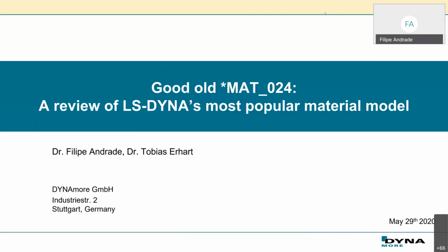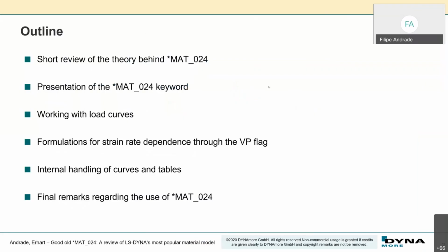So I'd like to start by giving you my outline. I will start with a very short review of the theory behind Mat24. It's just one slide, not much more than that. And then I will show you the keyword of Mat24. We'll talk a little bit about how to work with the load curves for this material model. And then we have a certain discussion about how to formulate strain rate dependence through the VP flag that you have in the keyword of Mat24.